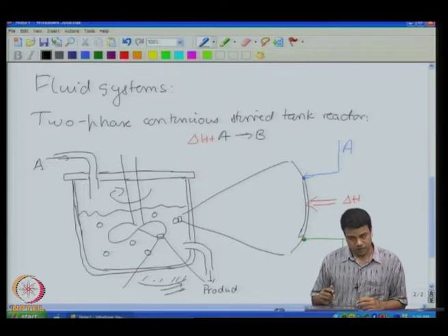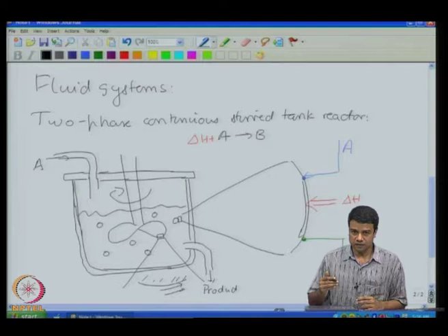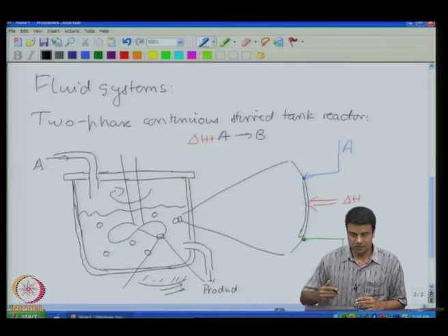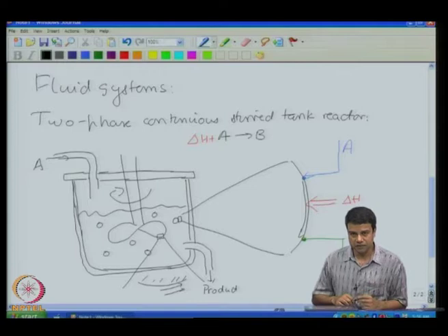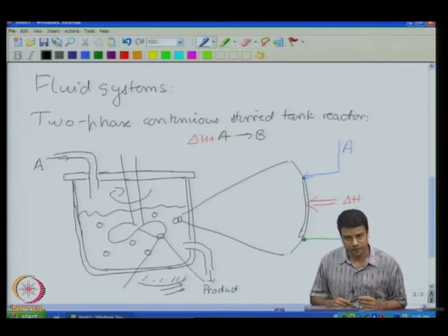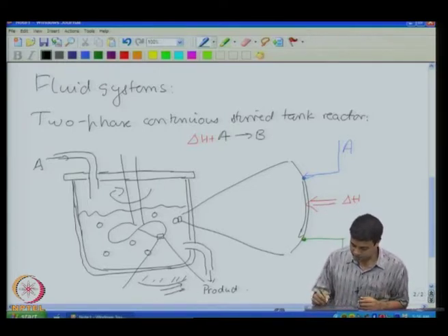The force, or rather the stress, which is the force per unit area that is exerted on the impeller surface, is actually a frictional stress. Stress is force per unit area and force is rate of change of momentum. So, the shear stress at the surface is actually the rate of change of momentum per unit area per unit time. So, it is transfer of momentum to the surface in order to compensate for the frictional losses in the fluid. So, this is a problem of momentum transfer.